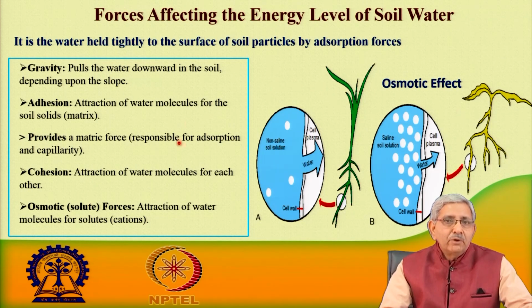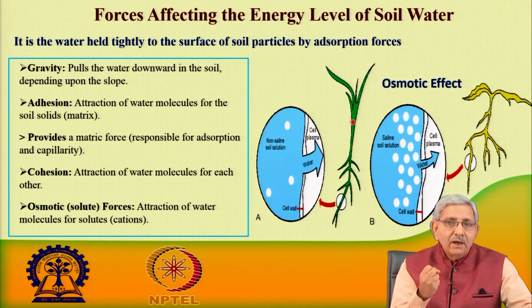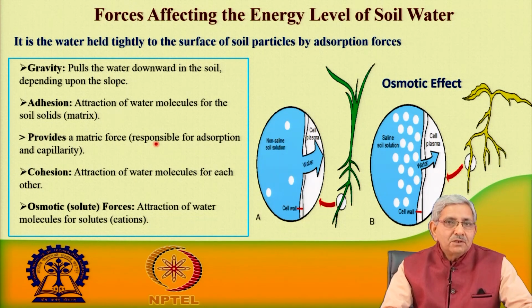There are some forces, and this is a very important part. One part is the water held tightly to the soil surface by adsorptive forces. So, there are forces acting, and the water is captured by the soil particles. Adhesive forces as well as cohesive forces are responsible for holding the water, that is the capillary water.